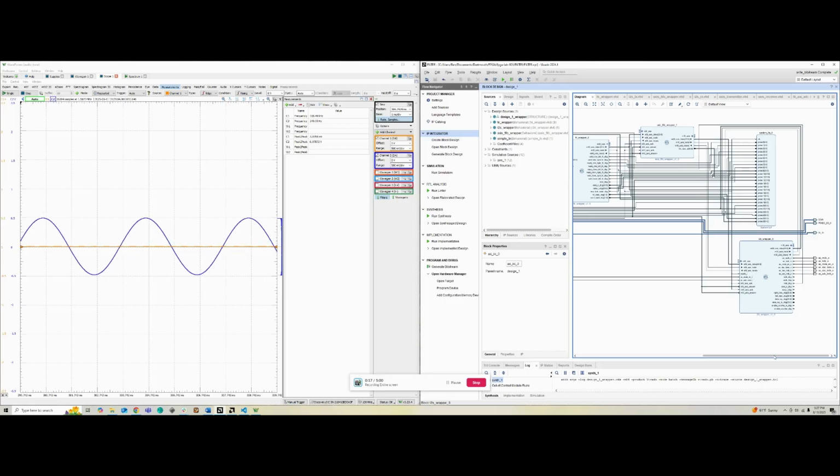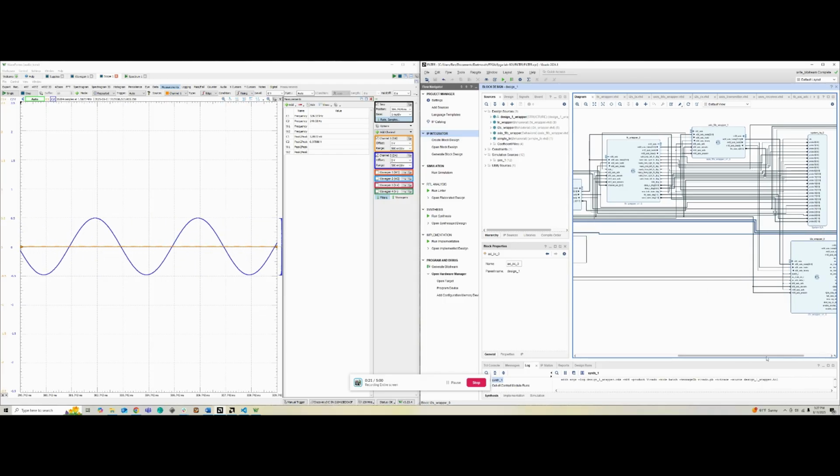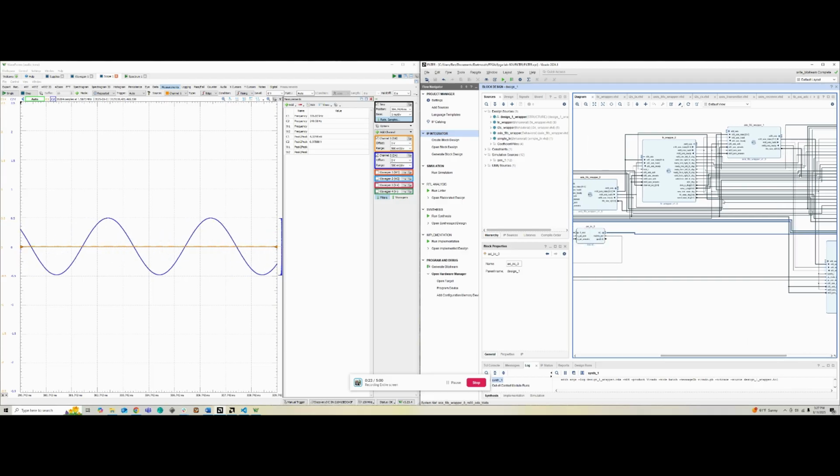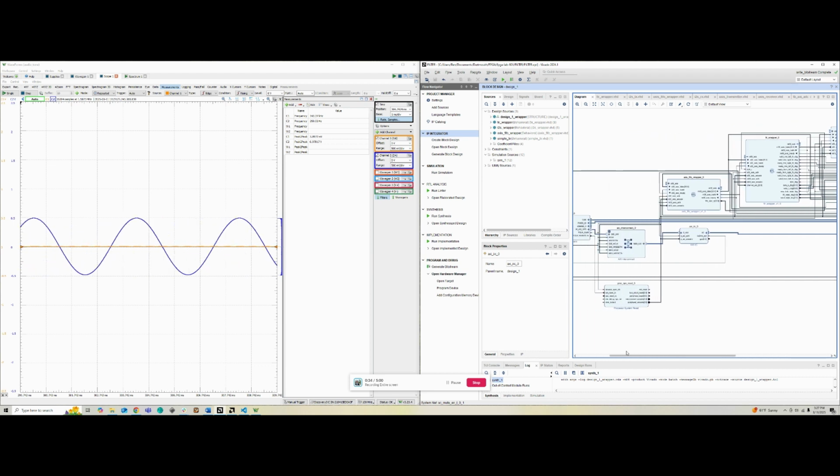In addition to this, I have two FIFOs using an AXI stream interface to communicate with the I2S wrapper, as well as the FIR wrapper between the two FIFOs that contains 8 filters of four different types with 2 filters, one for each side of the audio.